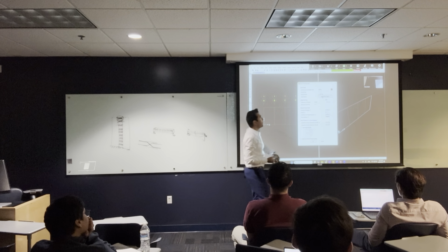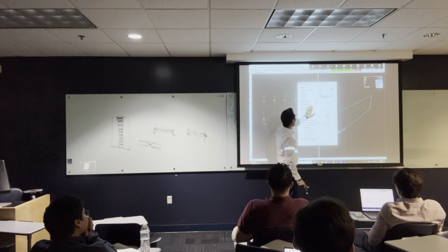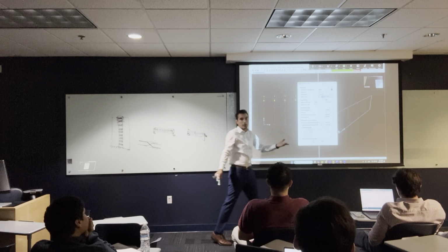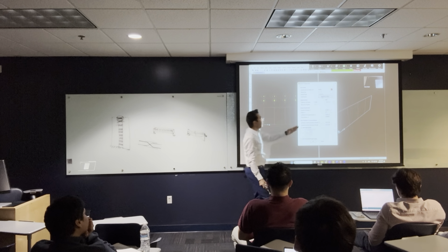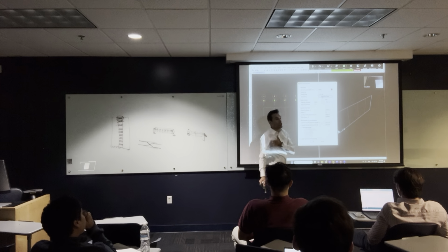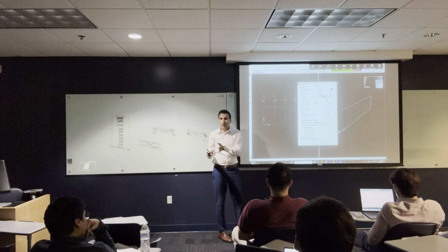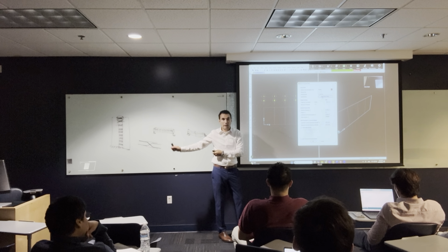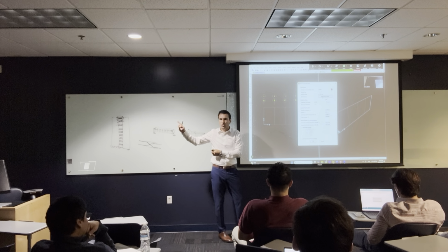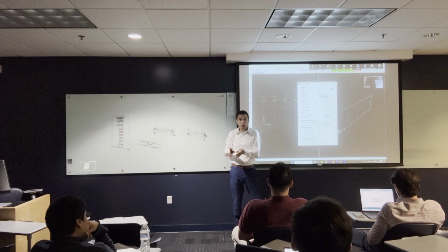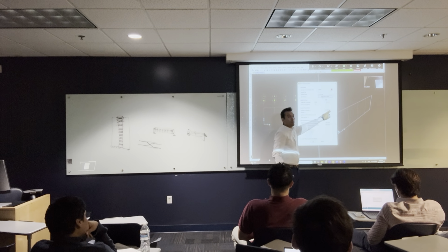So all I'm going to do is keep the 4,000. I'm going to check the weight per unit volume. It's 2.4. This is actually the density of the concrete, which is right. And here you are going to find the modulus of elasticity of the concrete. I showed you last time, if you want to calculate the modulus of elasticity of the concrete, you can do that. E is equal to 4,700 root FCU, the compressive strength. So if you know the compressive strength of your concrete, you can calculate this number.